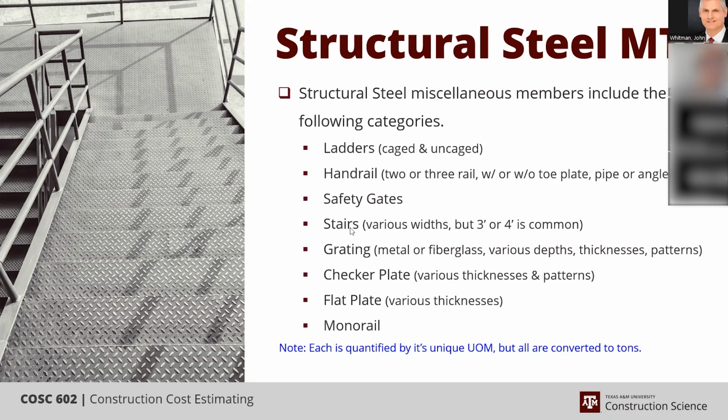And if you don't know any different, you can use that, and it runs about 9.1 pounds per square foot. But it's good to make sure, because if it's 1.5 inch deep bar and it's 1/4 inch thick bar, it's going to weigh a fair amount more than what I just quoted you. It'll go to like 10.7 pounds per square foot, something like that.